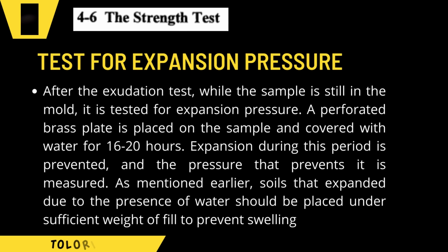Test for expansion pressure. After exudation test, while the sample is still in the mold, it is tested for expansion pressure after a perforated brass plate is placed on the sample and covered with water for 16 to 20 hours.